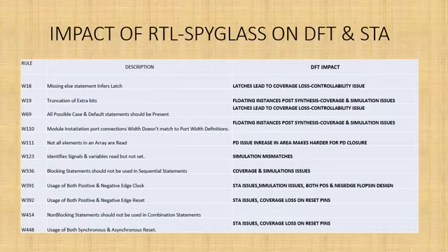Now, blocking statements should not be used in sequential elements, which will lead to coverage and simulation issues. Also, we should not use a mix of both positive and negative edge triggered clocks. Using both positive and negative edge flip-flops will lead to simulation failures because of wrong data capture.